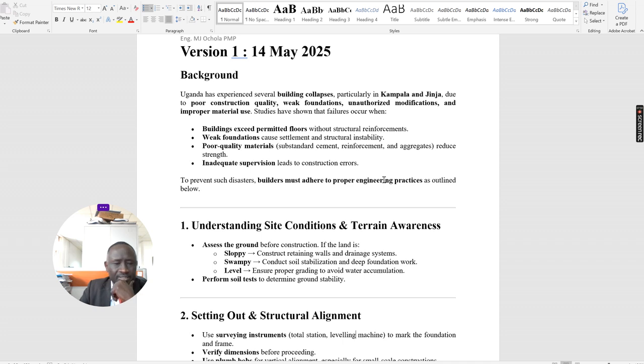and they're saying it looked like the design was for maybe 3 floors or 2 floors, and I think the employer or the client added 2 more. Definitely now that will lead to overloading of the lower supporting columns. So that's not very good.